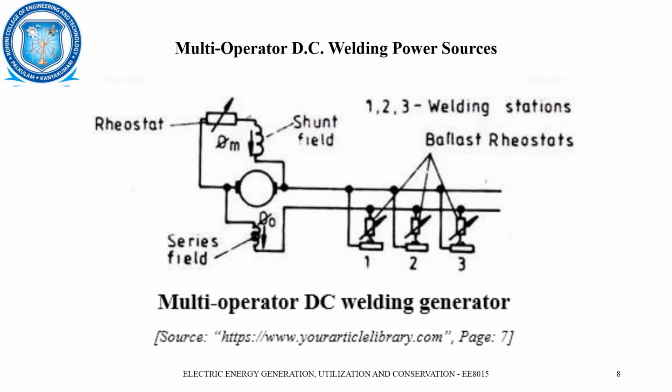They aid each other so that the magnetic flux of the series winding coincides with that of the shunt winding. In this case, the connection will be made. Because of this, the generator has a flat rather than drooping voltage ampere characteristic.